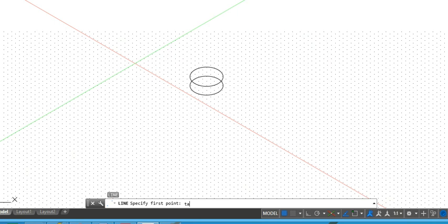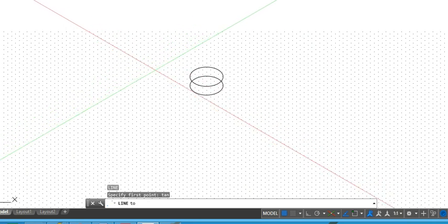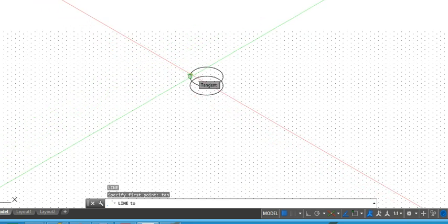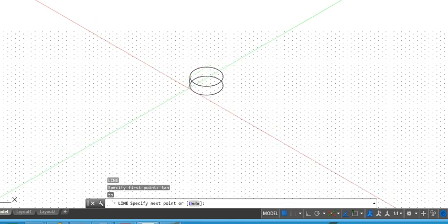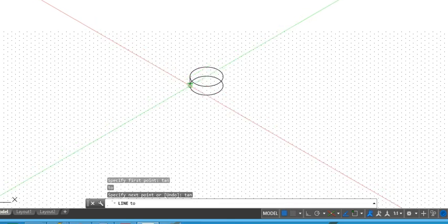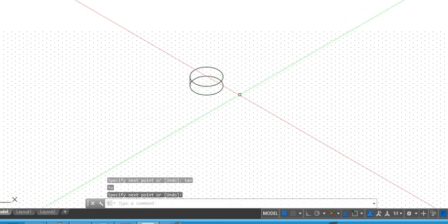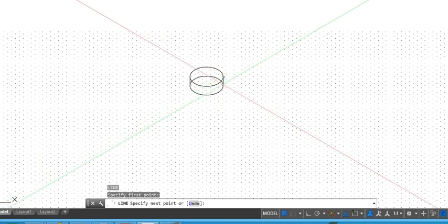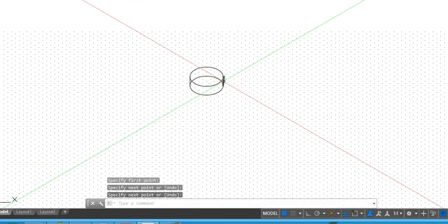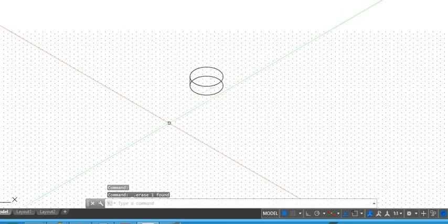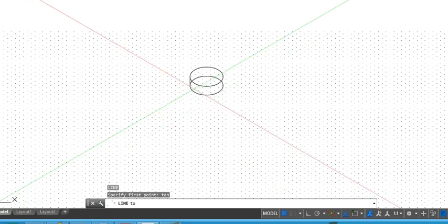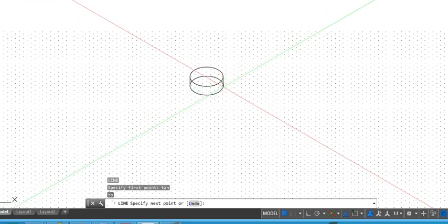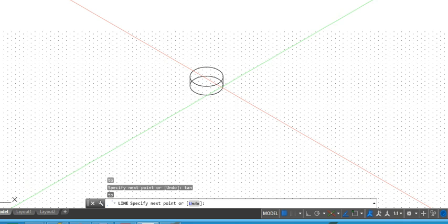Then again with the proper line command, with tangent to tangent, we can draw the exact tangent. Similarly on the other side we can draw an approximate line, so that AutoCAD will pick these tangent points, then we remove it. Then again the line command, tan to this one, and then tan to the other side.